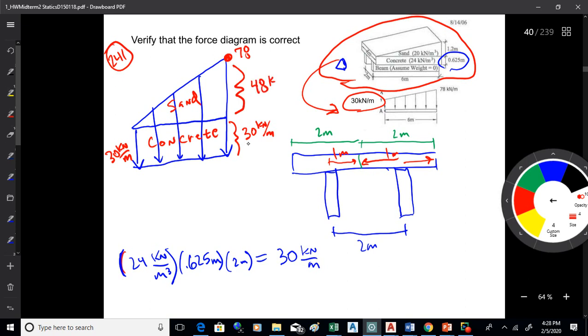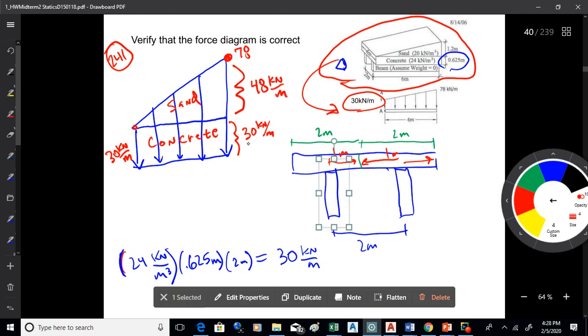So that's the sand the same way. All right, so that's how the sand's going to add up. Now the sand is going to start at 0, which is why that's right down there at 30, see? Because the sand area is divided by 2, because it's a triangle, right? It would be the same sort of calculation that I just ran: width times the height, but divided by 2, because it's a triangle, right? I would do that on the second step.